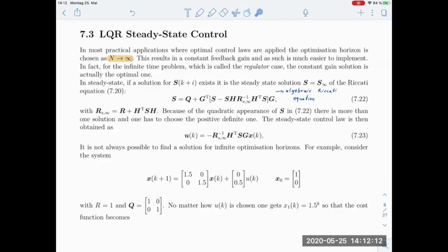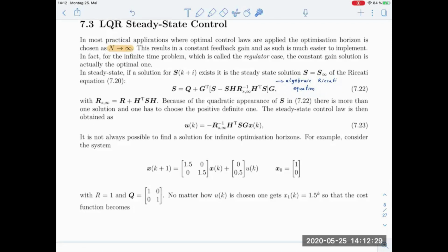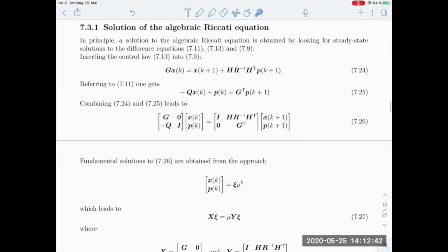Since we usually don't need to do that in an online fashion during the actual real-time run, but can do that offline, that's no problem at all. It's not that today's computing power is not extremely helpful, but it's just extremely efficient. There are extremely efficient algorithms to solve such Riccati equations nowadays. And that's in stark contrast to unstructured optimization problems, which die maybe after 20 or 100 variables. Of course, you can solve much larger problems, but it just takes more time and you have less structure and less guarantees. So long story short, let's solve the algebraic Riccati equation.